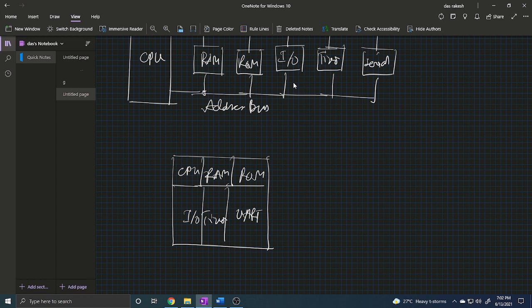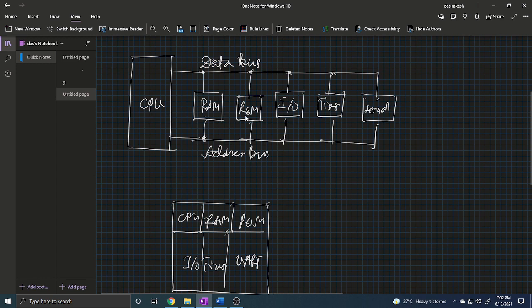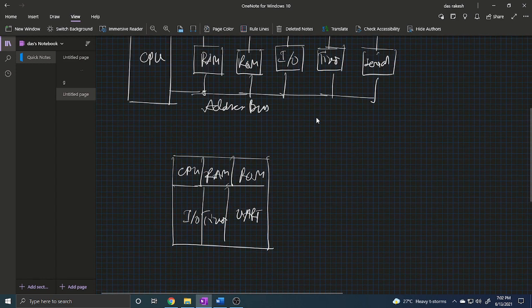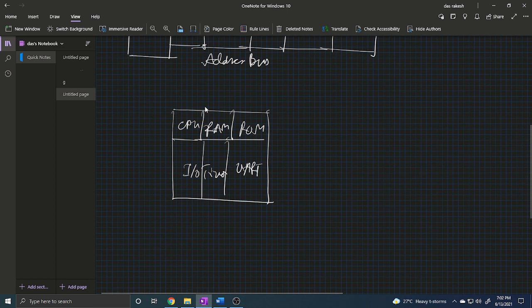And this is an advantage of the microcontroller over the microprocessor, because if we connect a microprocessor in a system, then we must develop the system board. That means with a microprocessor there is a connection of RAM, ROM, IO, timer, serial port, etc. There is a much more complicated design or development, but in a microcontroller all blocks are inbuilt within the microcontroller.